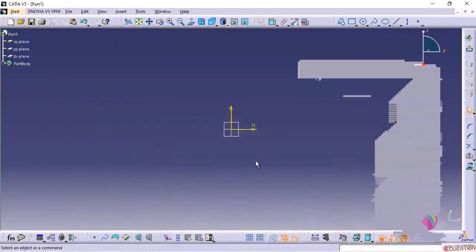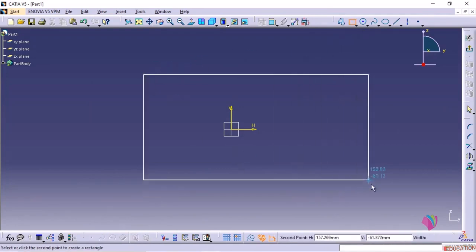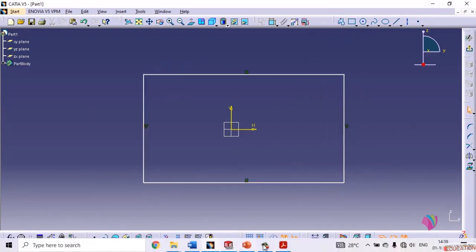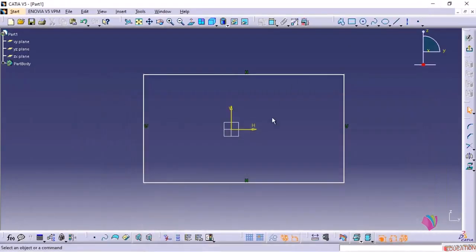Let us create a fully constrained geometry of the rectangle. I'll directly use the rectangle tool, or you can also go for 4 lines and create the rectangle. Let us take rectangle tool directly and create a rectangle something like this. In this type of drawings, it is always beneficial to create the circle center at the origin. So, the rectangle, or so to say the boundary, must be symmetric with respect to the axis. So what we will do is,